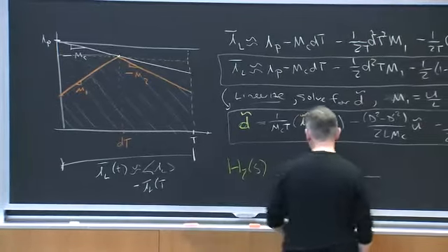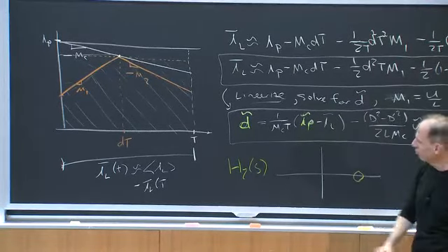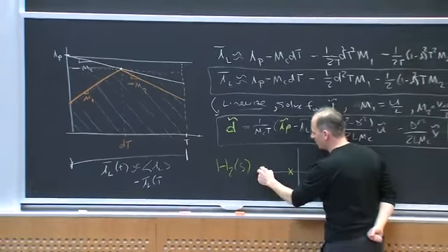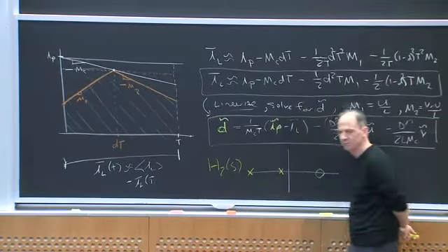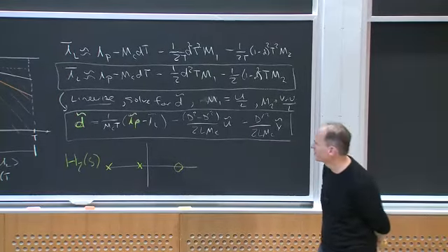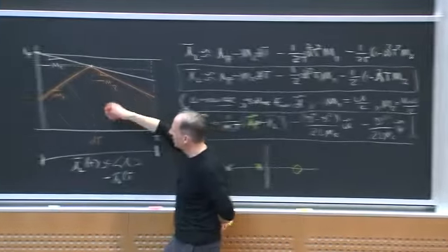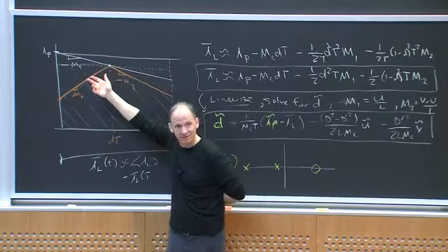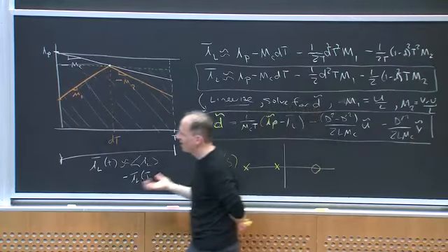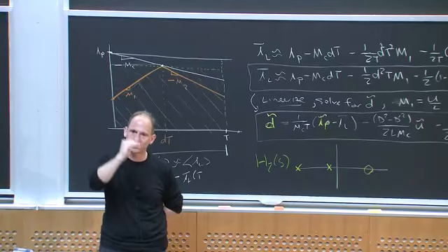The beautiful thing, however, is that instead of two really lightly damped poles, I'll tend to see a dominant pole and then a much higher frequency pole. Why? Because the way people like to think of it is this inner loop is making the current do what you want, and hence the dominant pole is more or less governed by how the current from that inductor feeds into the output capacitor and charges it up and down.